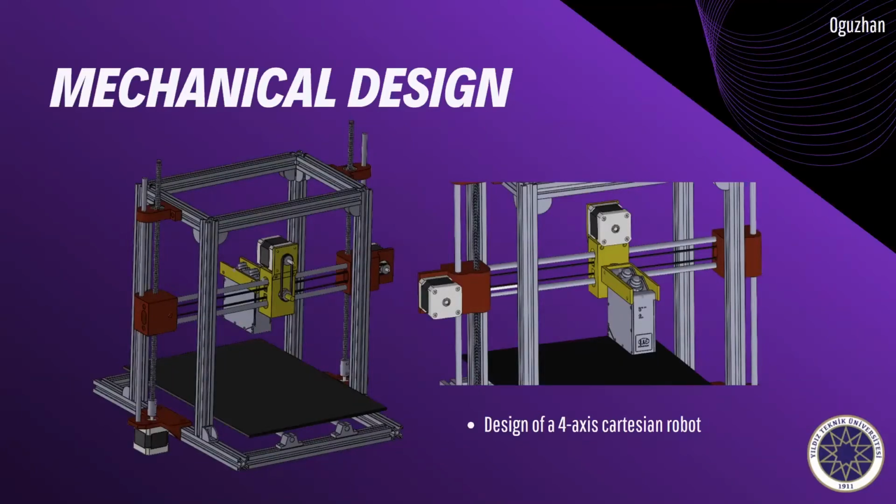In order to perform a precise defect detection, scanning has to be flawless. In the new design, our 4 axes will help us to have a good scanning result with its movement capability. Reflections are one of the biggest problems for the scanning process. To reduce reflections, a black platform is attached at the bottom. The black platform absorbs the reflected light and gives us more accurate scanning results. Power transmissions are made with power screws and belts.